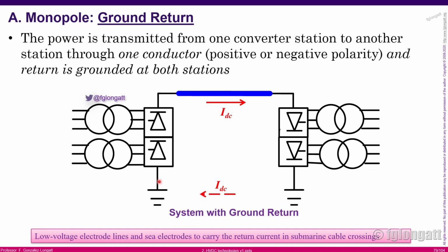There is a possibility of corrosion over there, and it could also be unsafe for people working near those electrodes, because the step voltage, the voltage at the ground, could be dangerously high, okay?